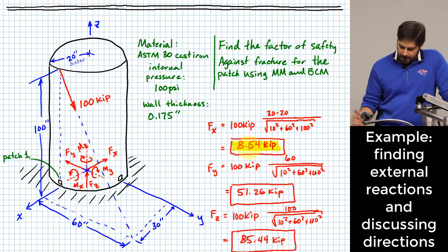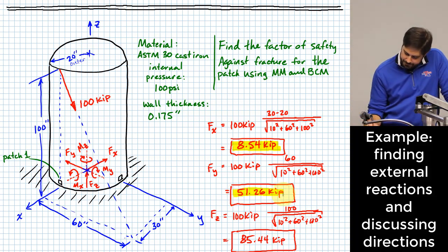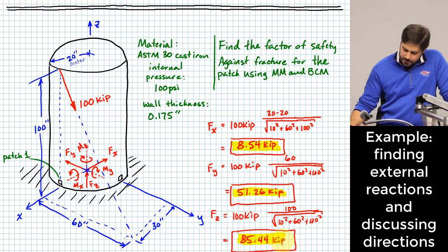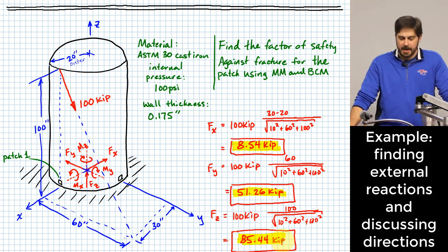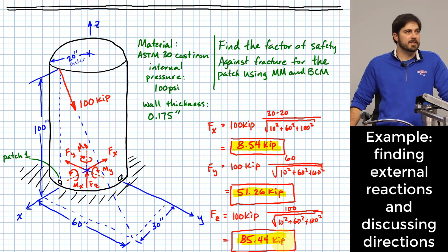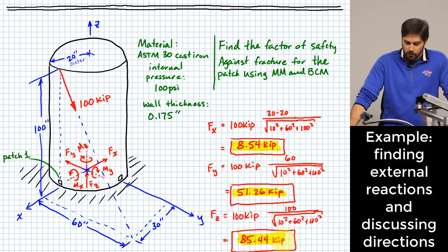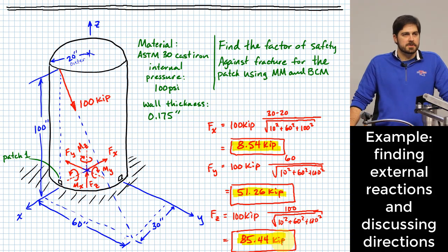Okay? You also see the Y direction and the Z direction. And these are the reaction forces that happen at the base. All right? One quick other comment that I will make that I don't think I mentioned yet. We are going to assume that where this tank is being supported at the base, the base is not supporting any of the hoop stress.